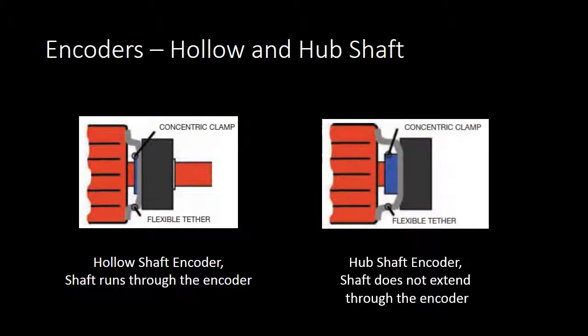Direct mounting has several advantages. It's easy to select for the correct shaft size and requires no alignment, and plastic inserts and flexible mountings provide mechanical and electrical isolation. But the disadvantage is the flexible mounting will lead to measurement inaccuracy in high accuracy applications.